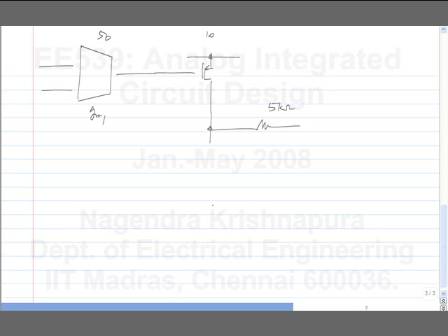If you do that, you know the load resistance. So what should be the GM of this? What should be the GM here? Yeah, 200 micro Siemens. So essentially you know this MOSFET, M11. Because you know what quiescent VGS there is, and you know the GM you want, so you know the size of the MOSFET. So you make the MOSFET. And of course, you also make a suitable current source on the other side.